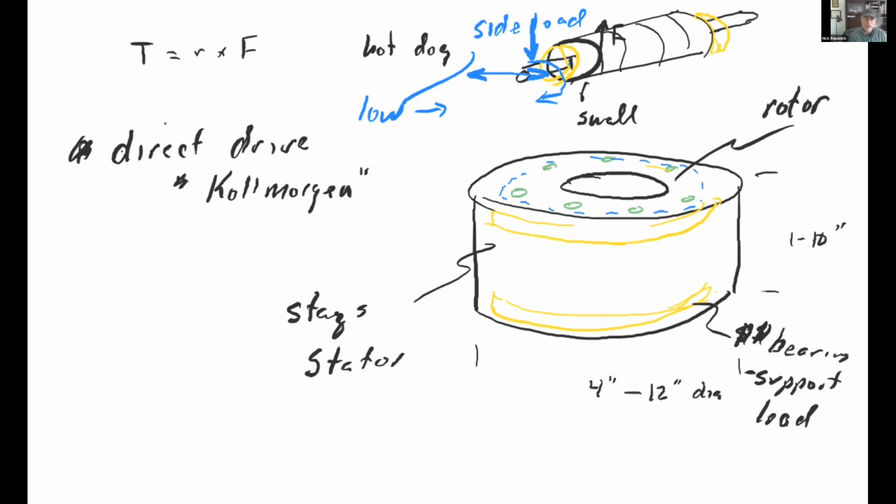When you start to add up the torque that you're able to get out of this motor and what diameter pulley, it easily gets used up. A NEMA 23 is just a few pounds of side load is all you're allowed to really put on that. And so one of the advantages of the direct drive motor, in order to do something with this, you then have to find a separate bearing.